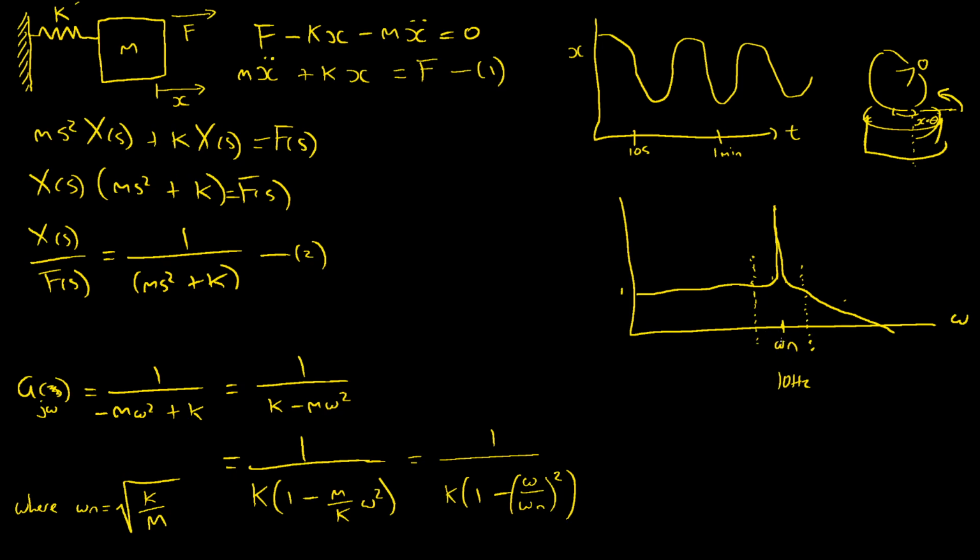And there's only two ways we can achieve that. The first one is to change either the spring constant or the mass, because they're the only things that can change this value. But generally with a physical thing, you can't just arbitrarily change it. There are certainly instances where you can. So in stabilizing adaptive mirrors and things, those mirrors have a frequency response that kind of looks like this, and they have low frequency resonant modes like this. And if your mirror is sort of sitting there on a mount, you can make a different mount, which will change the dampening and move this thing and might help.